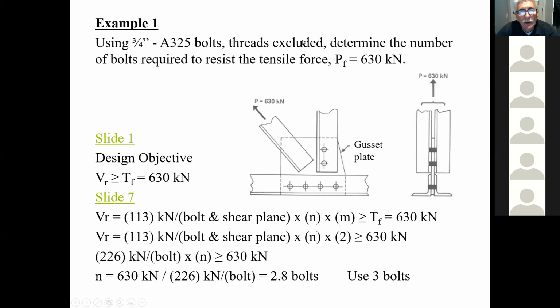Thank you for asking. Okay, so right now, you can appreciate that I'm going to be putting 3 bolts in here, right? Everybody sees that? Okay, so those are the 3 bolts, and now I would have 3 bolts in here, not 2. So here's one shear plane, Andrew, and here's another shear plane.